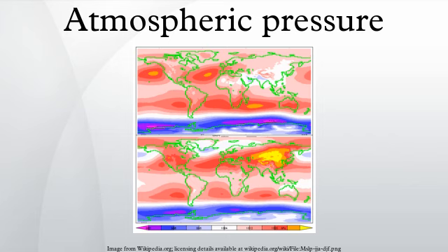Low pressures such as natural gas lines are sometimes specified in inches of water, typically written as WC or WG. A typical gas using residential appliance is rated for a maximum of 40 inches WC, which is approximately 35 hectopascals. In general, non-professional barometers are aneroid barometers or strain gauge based. See pressure measurement for a description of barometers.